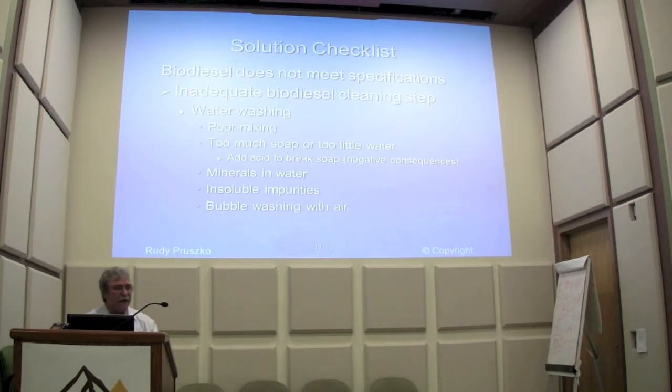The air can attack the biodiesel and actually start to break it down. So ideally you should use nitrogen. Now a lot of it depends on what feedstock you're using. If you're using soybean oil that has a lot of double bonds in it, it tends to degrade rather quickly if you bubble air through biodiesel that's made from soybean oil. So if you were using straight soybean oil, I'd say, hey, be aware of that. If you're using some of the other ones like animal fats that are more stable, they're very saturated, it's not as much of a problem to use air bubbling through.